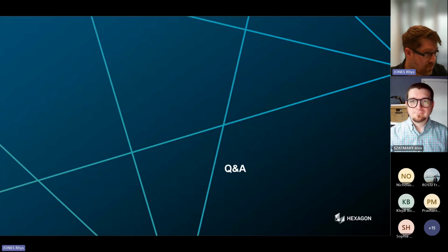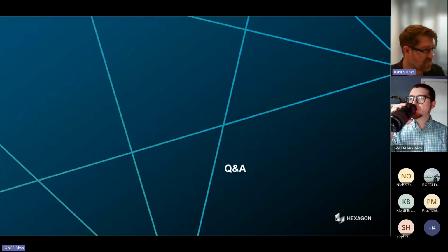So what we do is we go through a process where we reduce that into the stiffness coupling between the nodes. So we connect to certain points. So the shaft will have a point that we want to connect to our FE. So we want to know what the relative stiffness between that point and another point in our model is. We don't care what's going on in between in the other points, but we just want to know what those are.